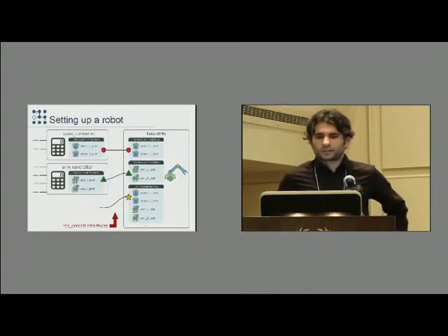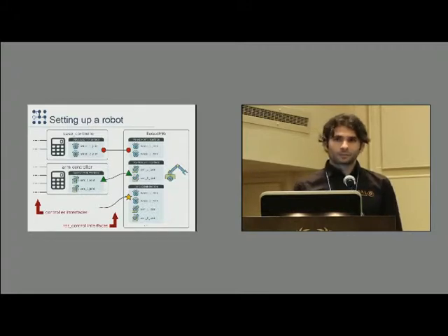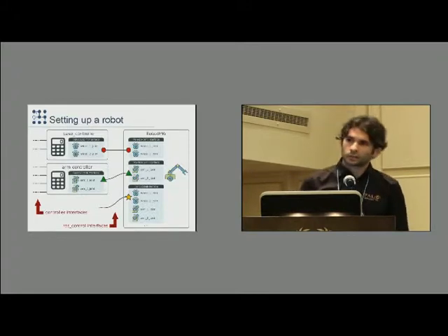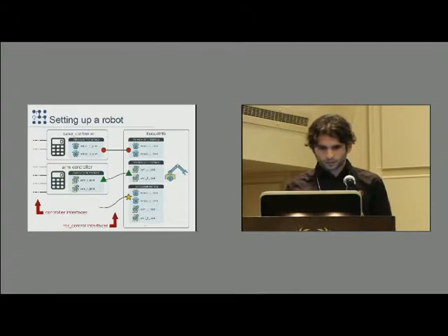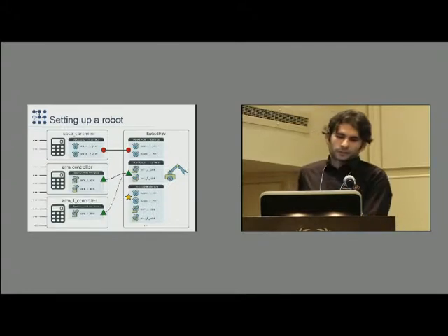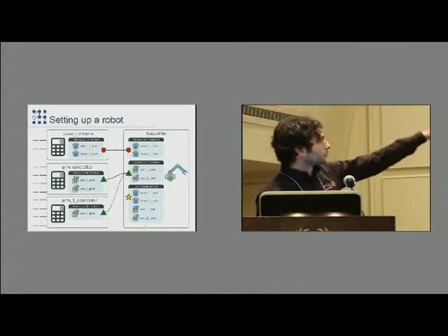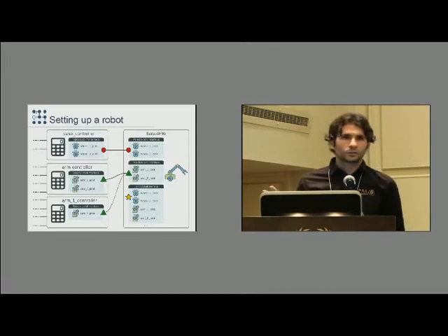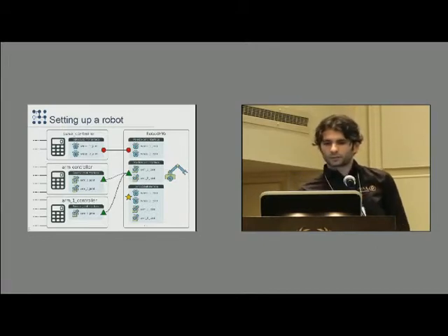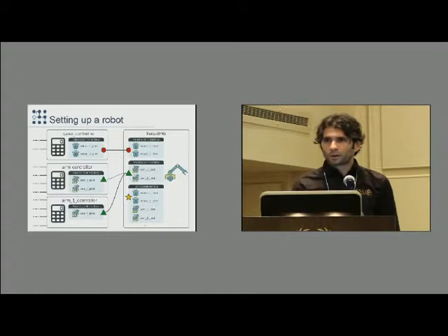So these interfaces connect with controllers, which are the guys that use them. And then at the leftmost part of the image, controllers have their interfaces, which this time are typically ROS interfaces: topics, actions, services. And they are custom, so your controller can expose whatever it wants. Something that is also relevant to mention is that you can have multiple controllers accessing the same interface, but in this case you can see that the two ARM controllers both use the first ARM joint. So by default there's a policy of exclusive resource ownership, so in this case you can have either one or the other, but not both running at the same time. This is enforced by ROS Control. If you want other policies, you can implement them as well.